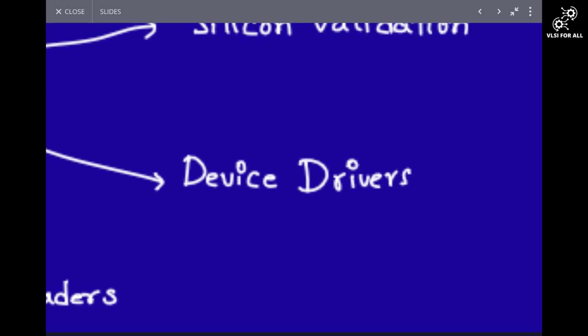A simple example for calibration: let's say my room temperature is 35 degrees. But at boot up, the sensor is giving actual temperature minus 10 degrees. That means 25 degrees, but 25 is not the right value, right? What we will do is program a register saying that whatever you are giving me as the output, add 10 to it. So if you're actually sensing the room temperature as 25, it will add 10 to it because we have written that 10 to a register in that sensor.